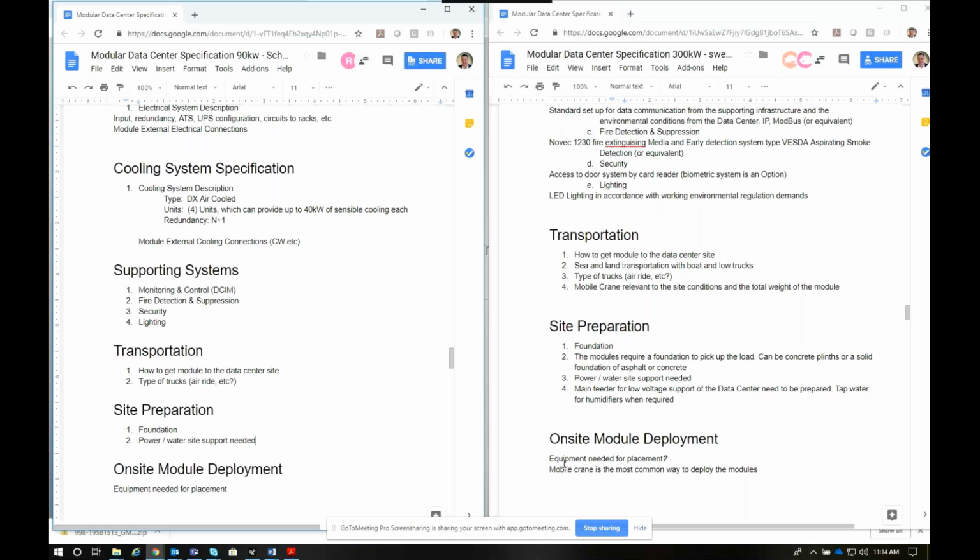So how generic can we be, you think, Rob, in this information here on site preparations? Yeah, just like you said, it's more like considerations. You must understand the center of gravity of the module being moved. Yeah. Also, obstacles that must be lifted over. When selecting a crane, consider these things.